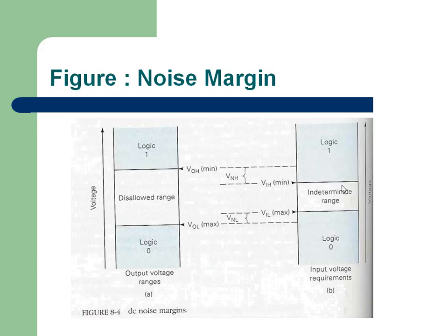And the condition that we discussed is called the metastable condition. So when a circuit goes into metastability, what can happen? There are two possibilities. One, the logic itself may come out wrong. Second, whether it is correct logic or wrong logic, it takes more time to settle.